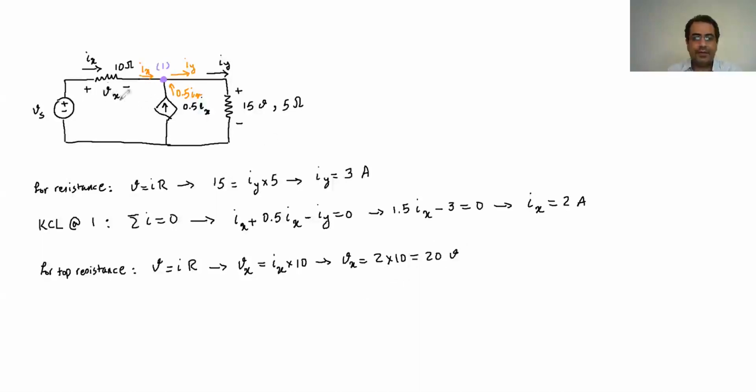So it's a Vx that we have here for this case. And now the only thing left is to find the voltage at this source. If I want the voltage, I have also 3 rules: the KVL, KCL, and Ohm's law. The KCL we write for the current, so it's not going to help us find the voltage here. Ohm's law is only for the resistor, so we can't use it here either. The only thing left is the KVL, the Kirchhoff voltage law.